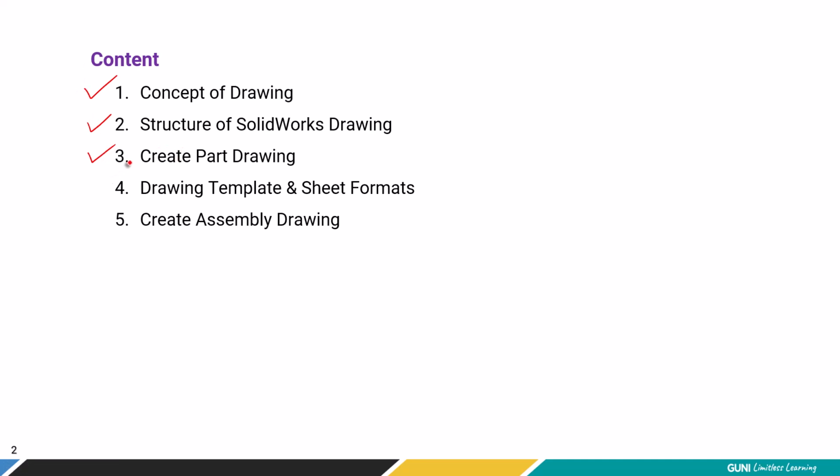After covering the part drawing, we are going to learn what is the importance of drawing template and sheet format. How can you use the benefit of this drawing template and sheet format to customize your drawing. And lastly, we're going to create an assembly drawing, in which we are going to create 2D views of the assembly along with the bill of material and balloons.